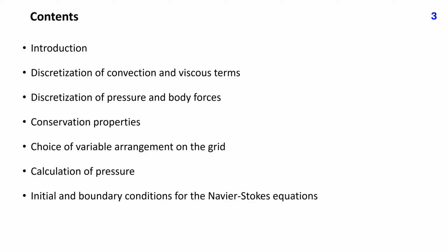It will be shown how a differential equation for pressure can be derived, but it is seldom used because of difficulties with boundary conditions. The initial and especially the boundary conditions for the Navier-Stokes equations require also special attention, in particular the conditions at solid walls and symmetry planes.